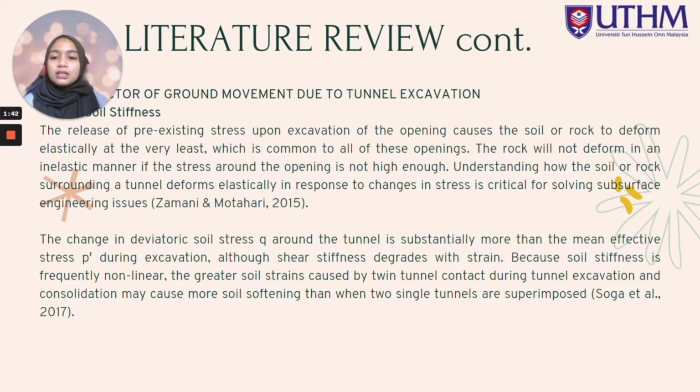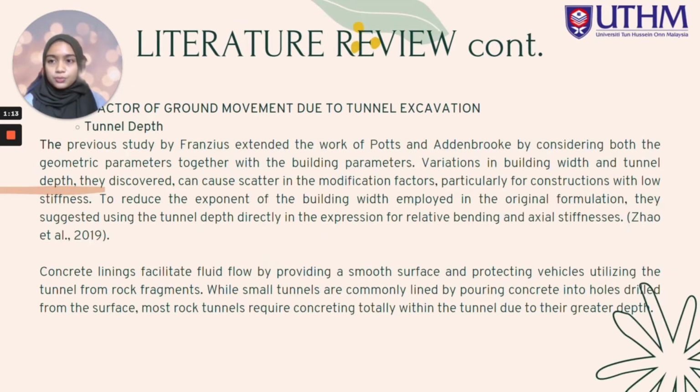The change in deviatoric soil stress around the tunnel is substantially more than the mean effective stress during excavation, although the shear stress deviates with strain because the soil stiffness is frequently nonlinear. The greatest soil strain caused by twin tunnel interaction during tunnel excavation and consolidation may cause more soil softening than when two single tunnels are superimposed. The next factor is tunnel depth.